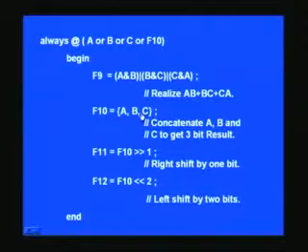Suppose you want C as the MSB, you should put C here, and then A comma B, in any order. Suppose in addition you want to add some 3 zeros at the LSB. All you have to do is put a comma here, and then say 3'b000, or any other data you want. If you put 111, 111 will be concatenated towards the LSB side, right? And so is the case.